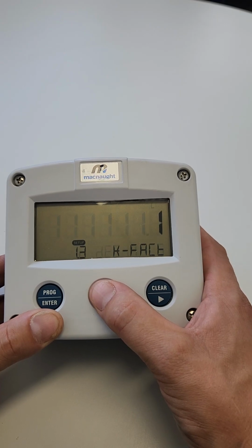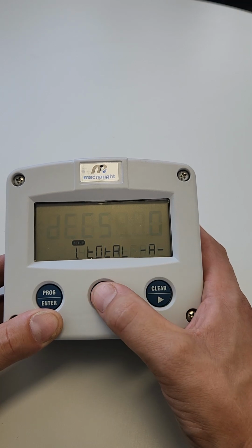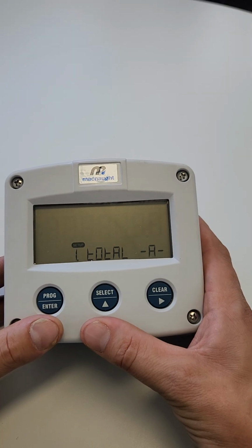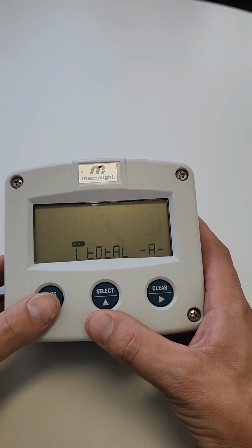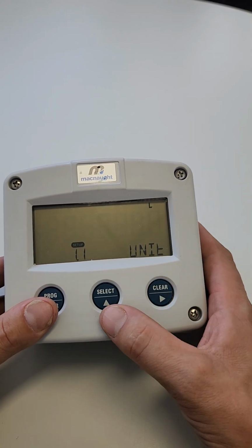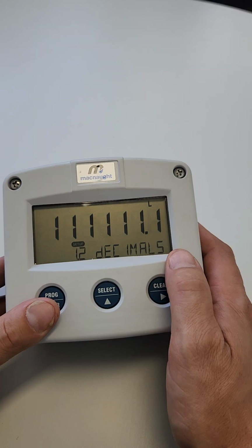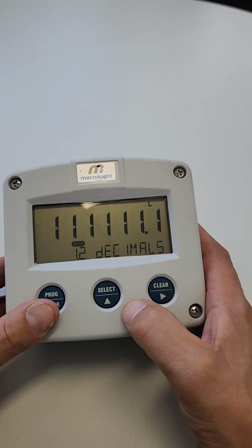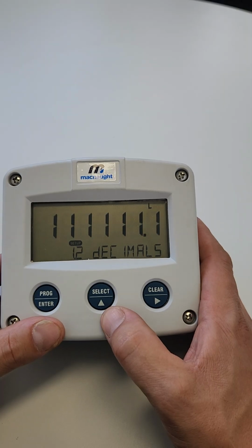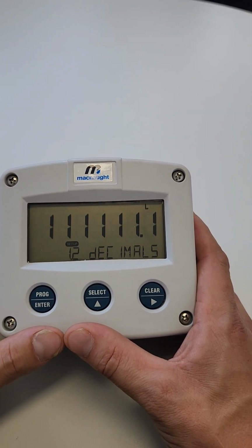We've got the unit, the decimals for the K factor itself, and then the K factor decimal place, and it'll take you back to number 1. The first one is unit, which is litres up the top, which is fine, which is what we want. If we go to number 2, which is the decimal places for the K factor. The K factor we are using for the bulk diesel is 6.69, which is the MX50, which is what we use in our service trucks.